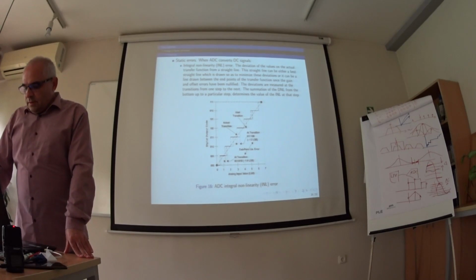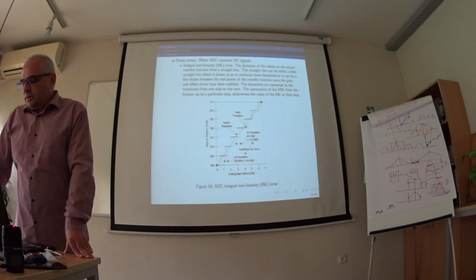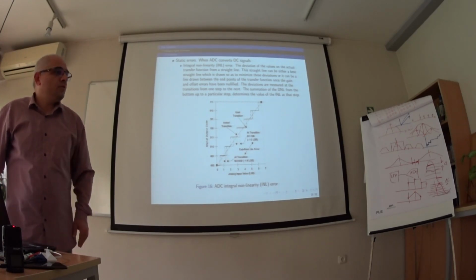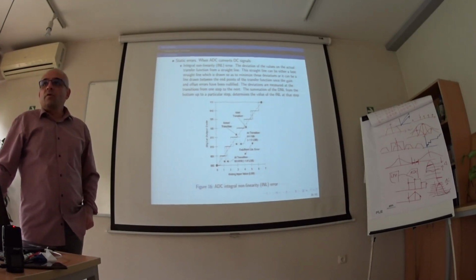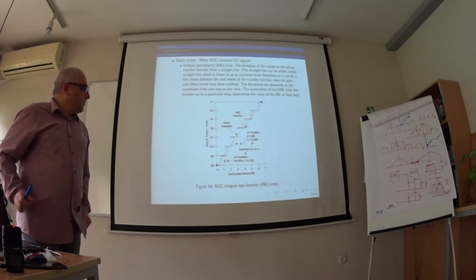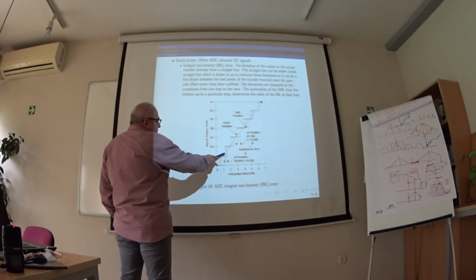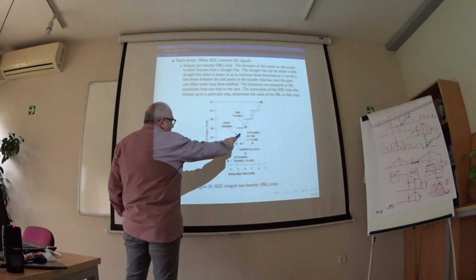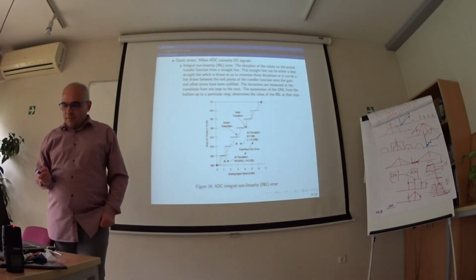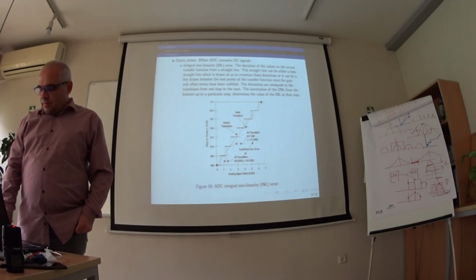The second one is the integral nonlinearity. As the name suggests, this error is measured by summing or integrating the differential non-linearity. Up to this point, let's say, we accumulate every differential non-linearity and we get the integral non-linearity. Usually, the manufacturers specify such an error as its maximum.